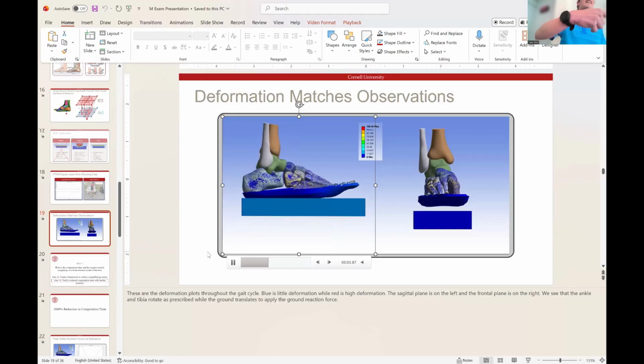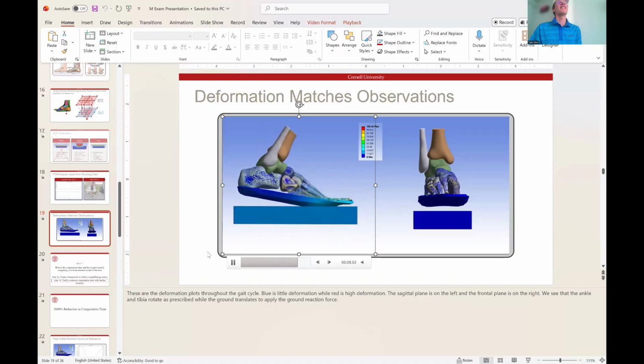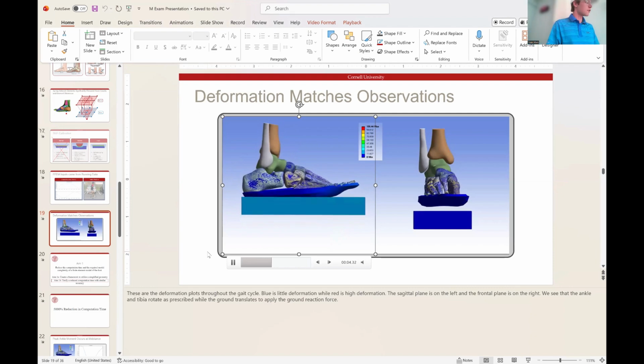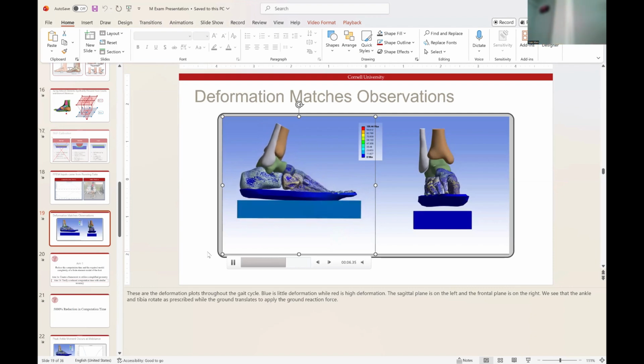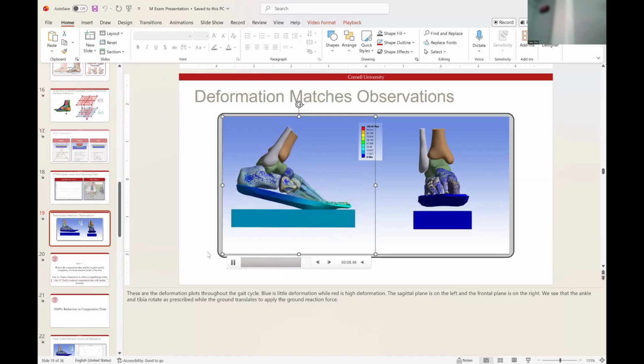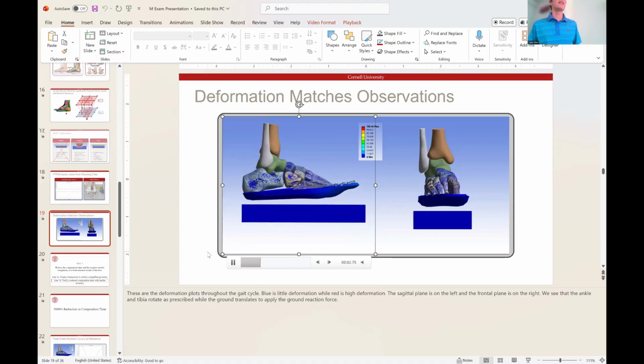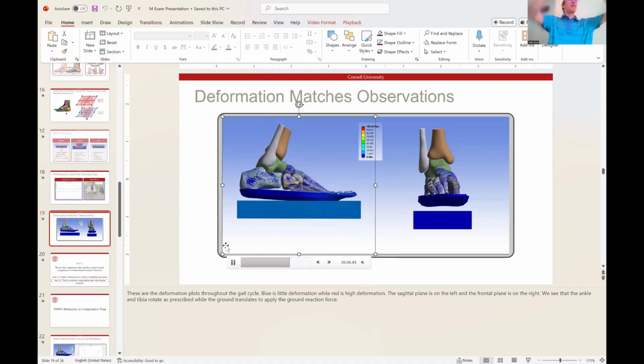And that way I trick it into creating a mesh around the surface of the rigid body. But it's not slowing down the solver because I put a tolerance on it of, say, 1 millimeter. Since I placed the contact surface on the bottom of the ground, the bones are not even close to it. It's not going to recognize the contact and it's not going to slow it down. So is it effectively like a? Yeah, it just wraps around it.